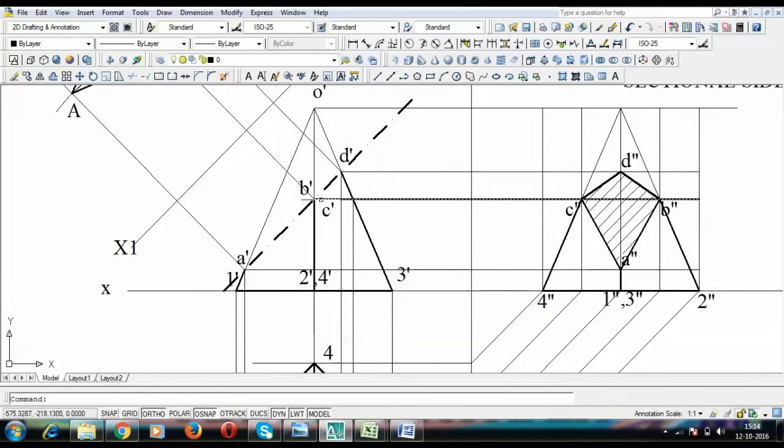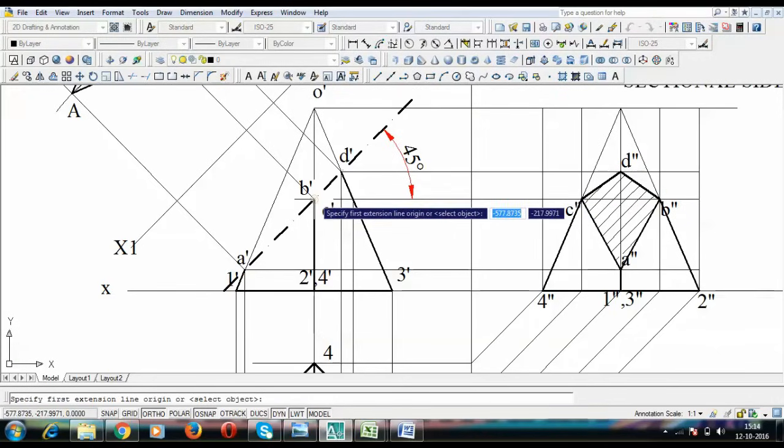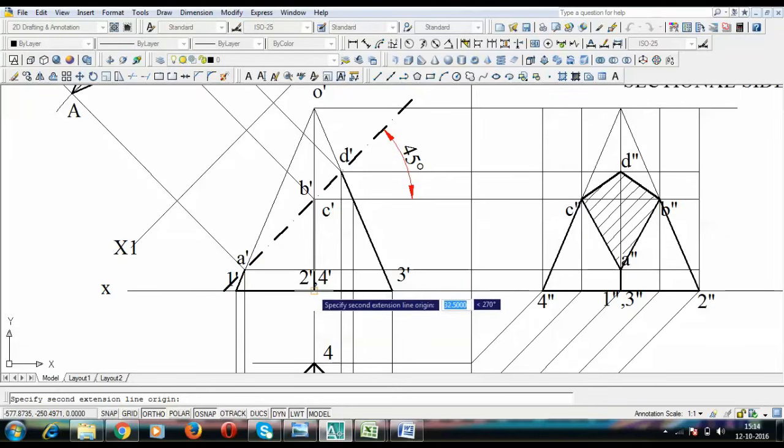And this over here is the center point of this axis, through which the cutting plane passes at an angle of 45 degrees. The distance over here is 32.5, since it is bisecting the axis, and the axis was 65. It is showing as 33 millimeters, but it is 32.5. Trust me, take my word. It has been rounded up to 0 decimal places, maybe that's why.